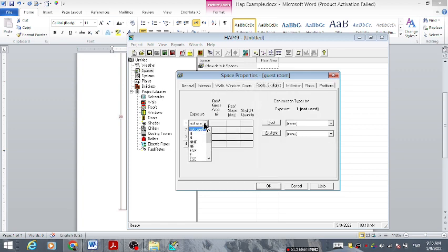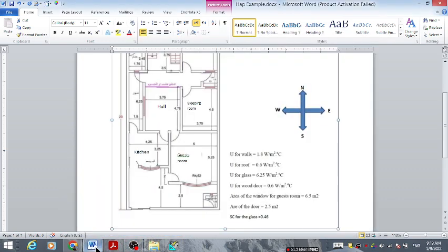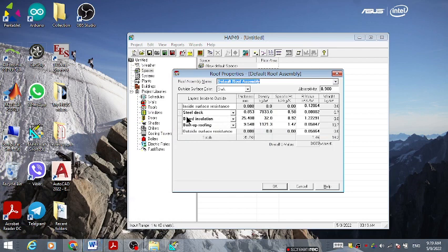Now going to roof. The type of roof is horizontal, area 26.3. Do you have a skylight? No. Now you need to define your roof. Roof U value is 0.6. It's concrete. So okay, inside steel deck. If you have deck, concrete, it's low weight concrete, built up, gypsum board from outside, insulation, board insulation. See, this is okay.